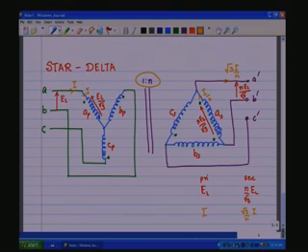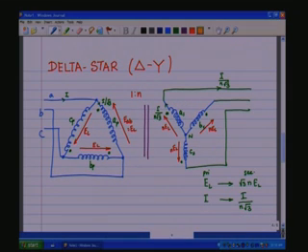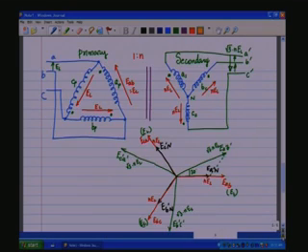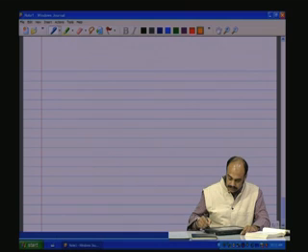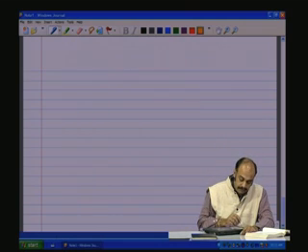So, this is the relationship between the primary and the secondary side currents, the star delta. Basically, it is the reverse of the delta star what you saw here. In the delta star, EL becomes root 3 n EL, and when you apply I, what you get at the output is 1 by n root 3. The flow of power is just reversed, and the phasor diagram is likewise similar in the case of star delta.